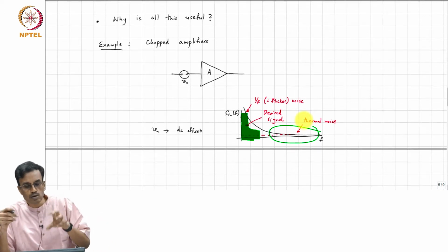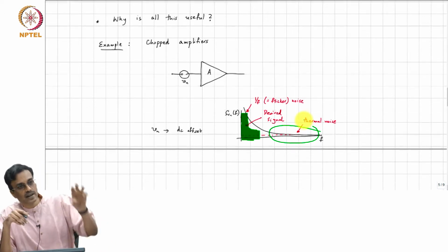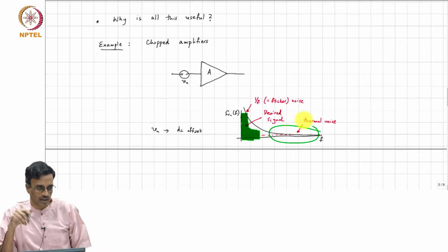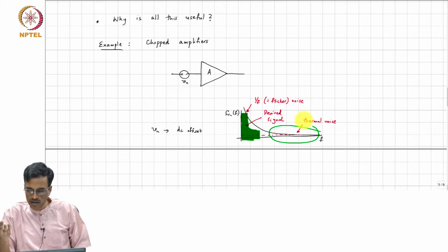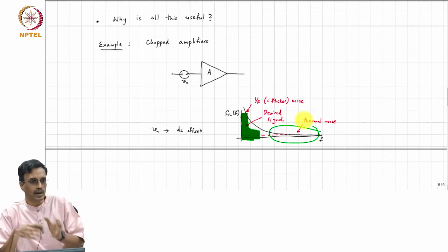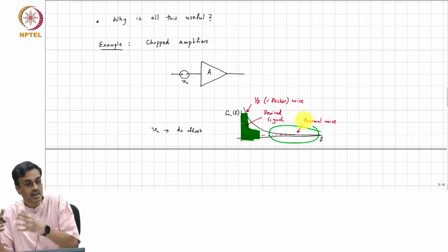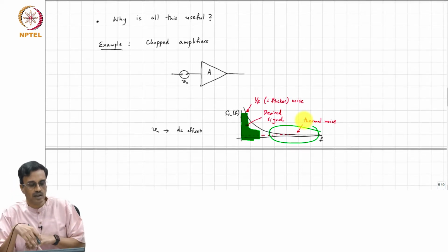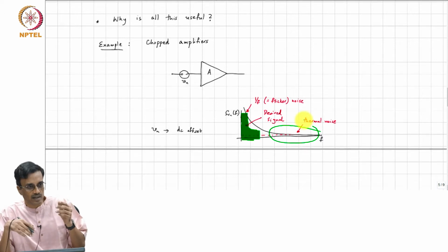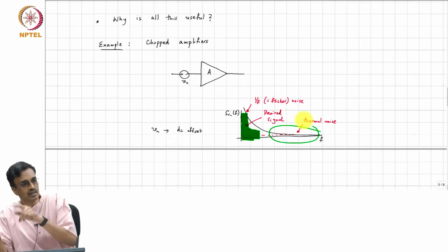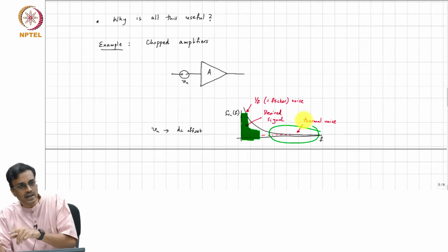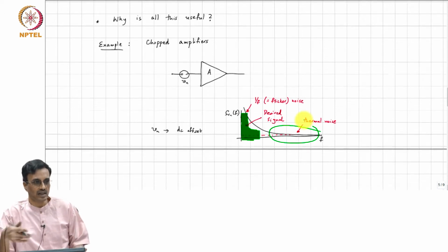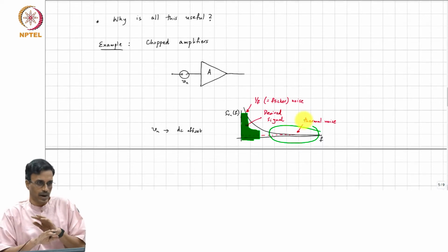You go there and then you amplify the modulated signal at high frequency. I mean, you take the input signal, you modulate it to a high frequency, high enough that you know that the amplifier's noise is only thermal at that point, and you amplify it. The amplified signal will still be at this high frequency, and then you can demodulate the amplified signal back to baseband, right.